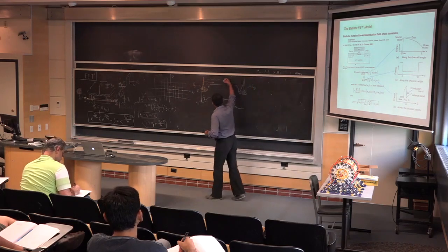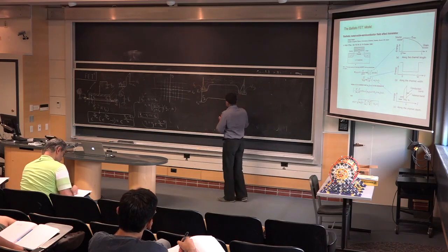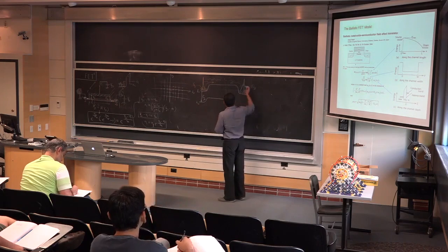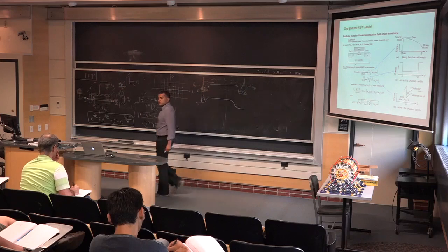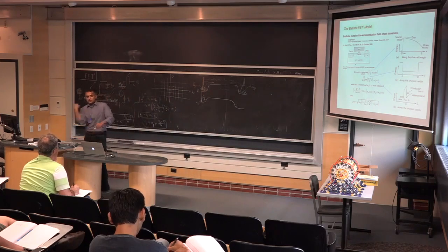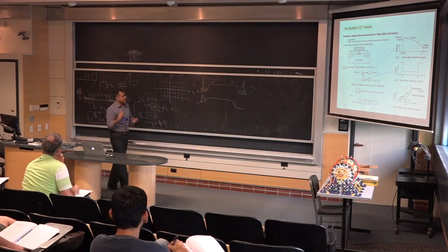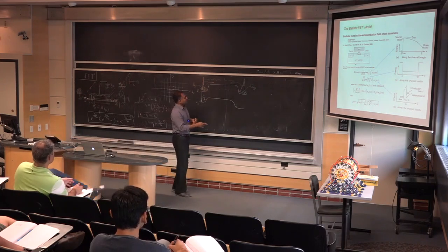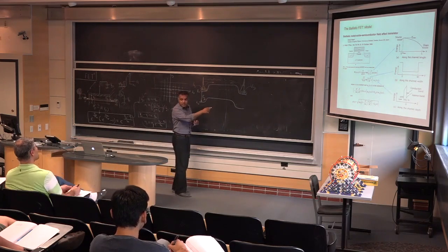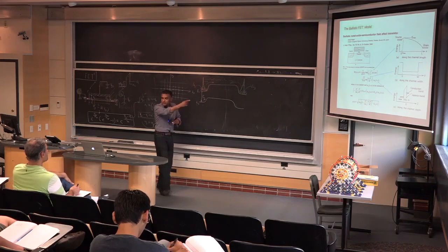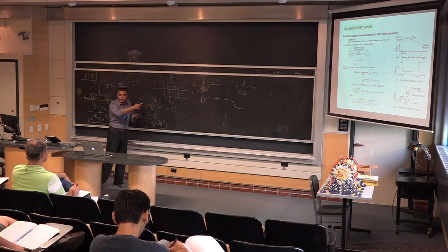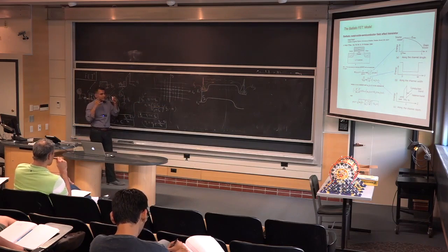Similarly, an electron getting injected from here, from the drain, is also moving ballistically. And so there's no mixing between the two. Does that make sense? I mean, an electron cannot turn around and go back to the other. That's the meaning of there's no scattering. If an electron gets injected, it keeps going in the same direction. It doesn't waver in its orientation of velocity. Right? I mean, ballistic, that's the meaning of ballistic. It doesn't change its direction. Once it's injected, it keeps going.